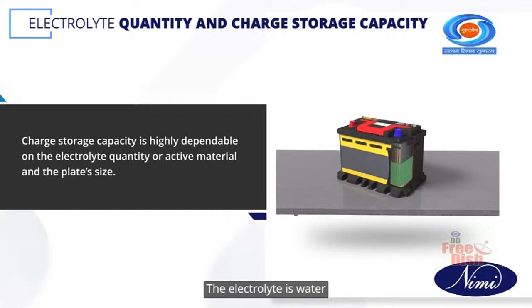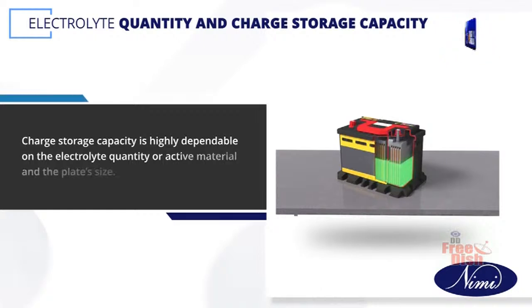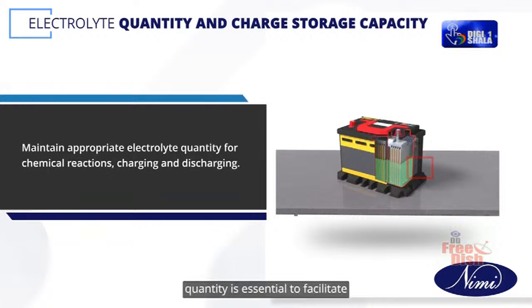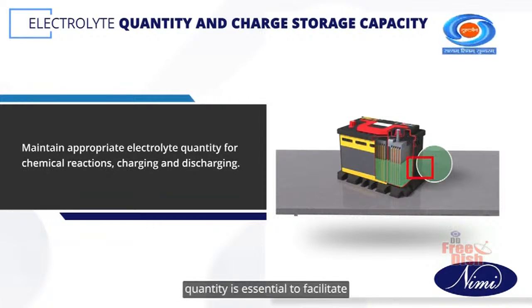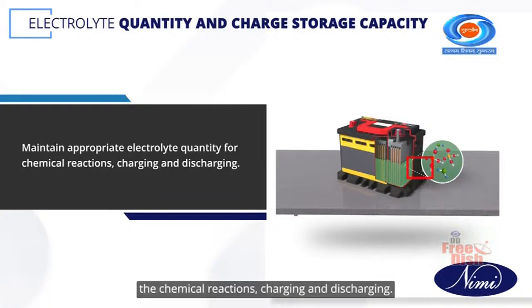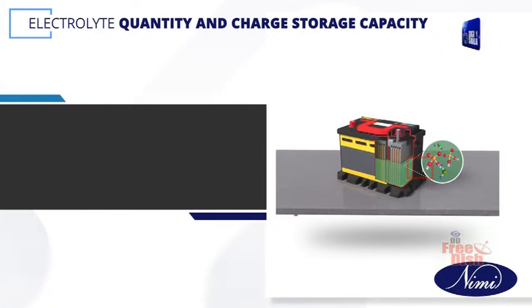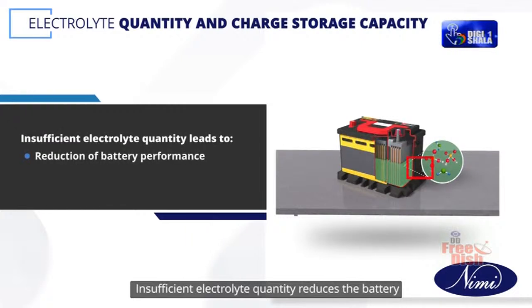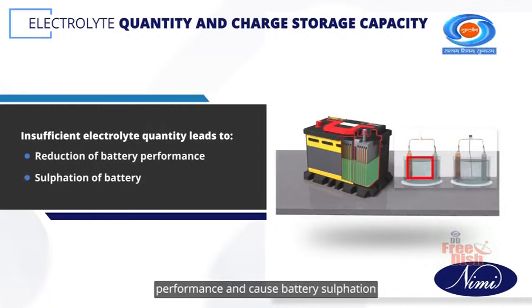The electrolyte is water and sulfuric acid. Maintaining the appropriate electrolyte quantity is essential to facilitate the chemical reactions, charging and discharging. Insufficient electrolyte quantity reduces the battery performance and causes battery sulfation.